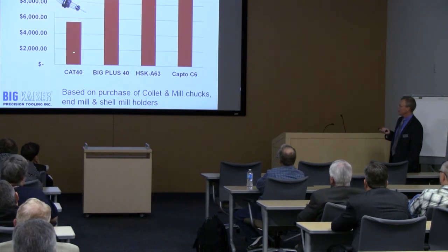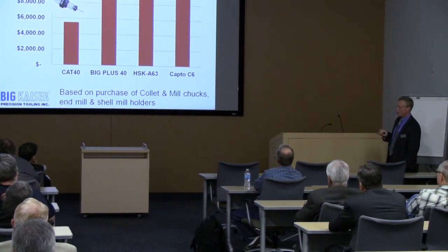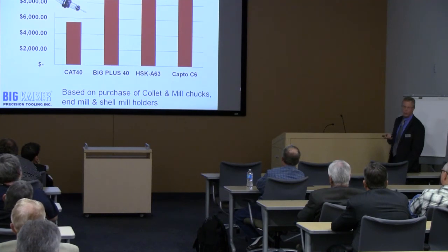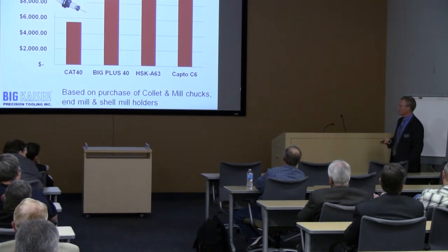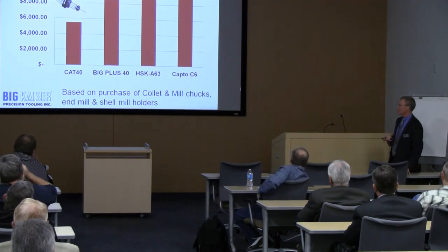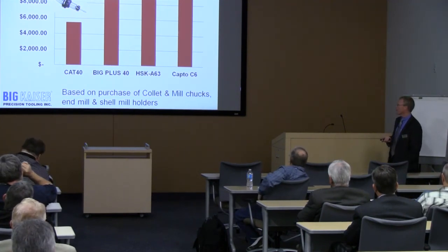In the case of Big Plus and Cat 40, though, I can select the lower demanding operations to use standard Cat tools, and the higher demanding tools to use Big Plus in mix and match. Although it's not our first recommendation, it can be done. That's the way the system was designed, and it can be used. And it is used in practice by many customers throughout the country.